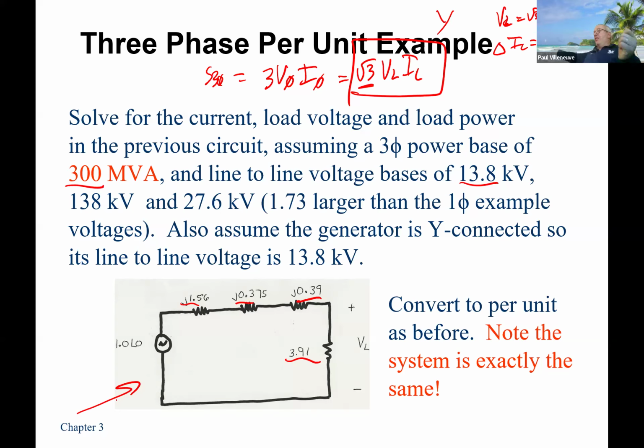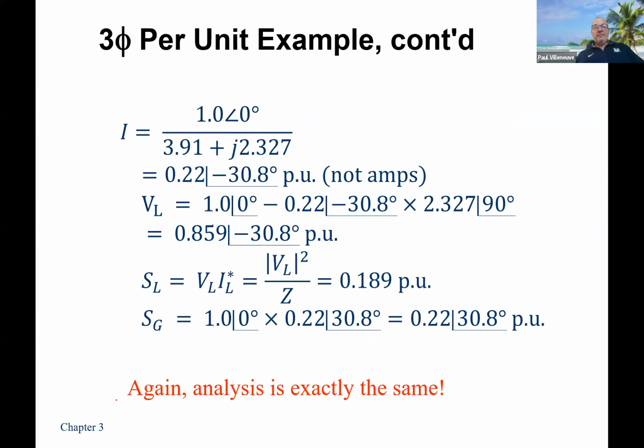As long as you convert it to single phase equivalent, which means all those impedances are actual resistors, inductors, or capacitors, those are actual ohmic values. When we adjust our voltages and our power, that will take into account how the system is configured, delta or Y. And that will help us get through that. Questions on that?